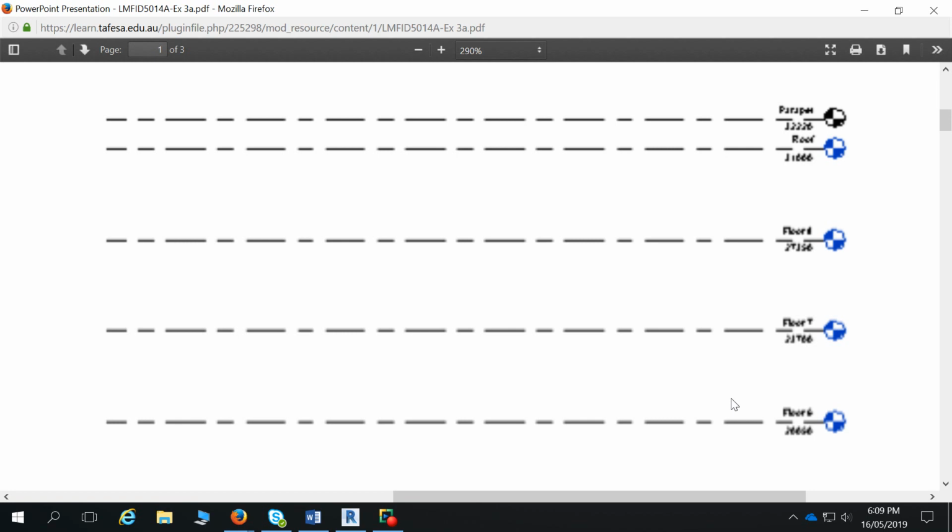If you want to have a run through that in your own time, feel free, but we're going to run through setting up levels for probably a double story tonight, and then it's the same practice for a single story. Then we'll put some grids in the project, and then we'll jump onto the DWG, because I'm sure you all want to draw a house and not all the setup stuff. It does help if you have levels set up in your template, because then you don't have to do this process again. You can always delete the top ones out if you're only drawing a single story. It makes it a bit easier than putting levels in.